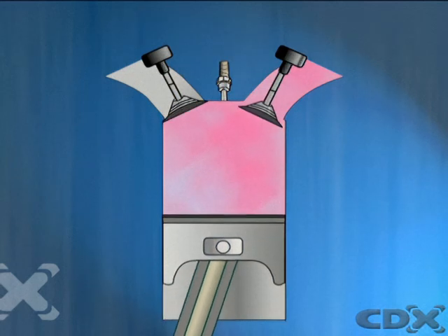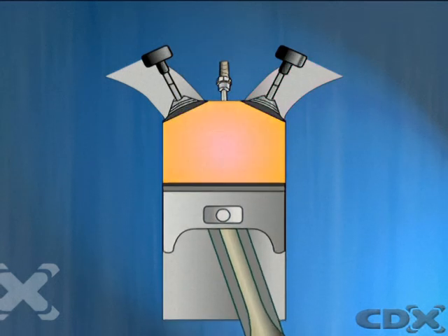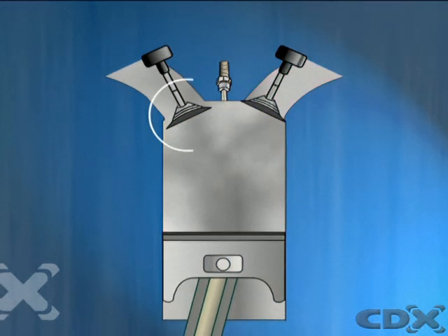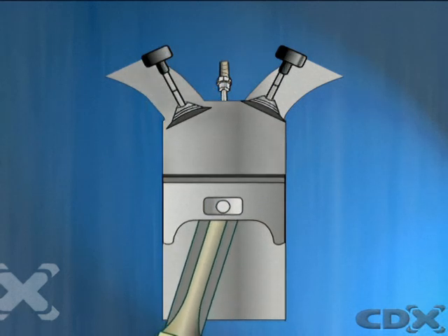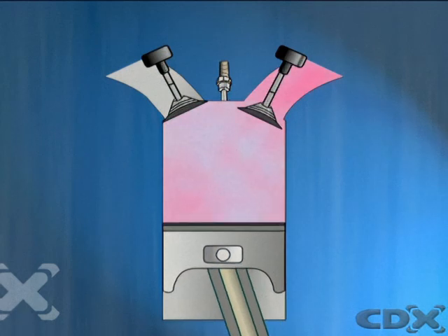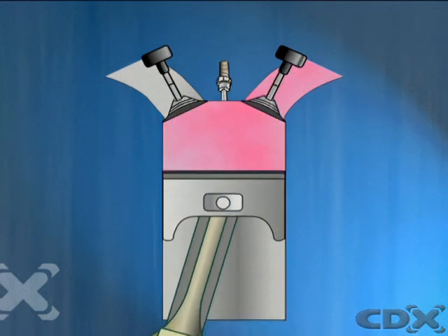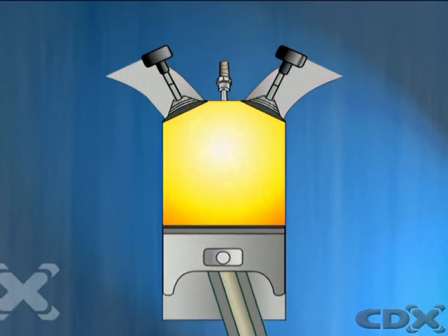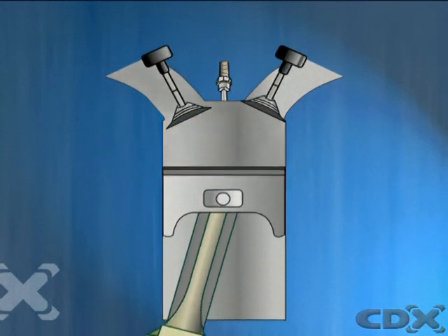The effective expansion stroke is lengthened by delaying the opening of the exhaust valve, so all the pressure created by the expansion of the combustion gases can act on the piston until they're completely dissipated, applying pressure to the crankshaft for a longer period and increasing efficiency.